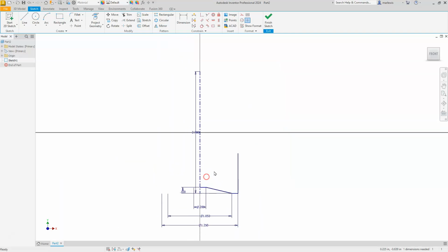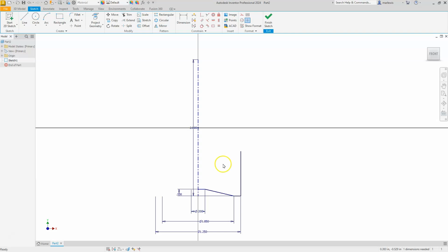I'm just going to zoom out a little bit to create my next point here, and I've got 2 different ways I can do that, right? I'm just going to pull this down a little bit. I can either create a couple of vertical and horizontal lines, or I can create a line up here and create that arc along it. I think in our case, let's go ahead and create the 2 lines, and it'll make it a little bit easier for us. So let's draw a line from this endpoint. Try not to keep it in line with anything else, and then go straight up from here.